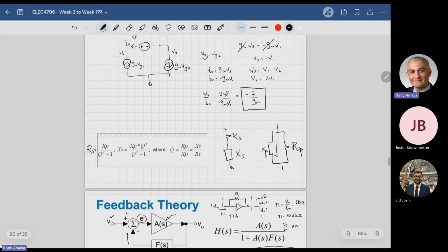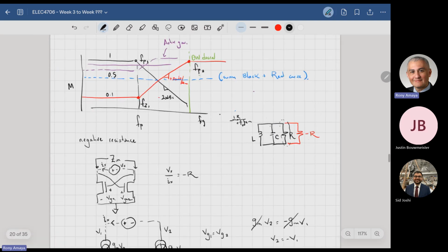So in the oscillator that I was showing you, you can easily take the resistance from the metal, which is the series resistance you see here, and the conductance, which is a resistance by definition, and you can combine them together to form this RP. But one of the neat things about it, and I said in class, is that we can actually generate negative resistance. And why am I bothering with this? Because along the way, along with channel inversion and losses in systems like high-speed systems, we will encounter circuits that will benefit from having negative resistance. How do you analyze it?